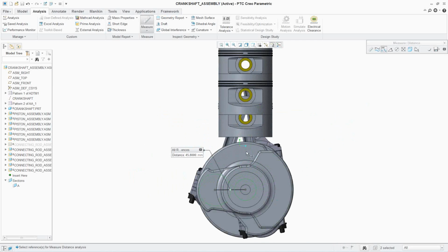So this is the crankshaft. It's going to rotate around. And when this point here, the point where the connecting rod connects the piston to the crankshaft, gets to the top, that piston is going to be at its peak height. And when it rotates back around to the bottom, that piston will be at its bottom height, what I showed in the diagram in the Mathcad worksheet. So this distance here is half of the total distance the piston will move up and down.